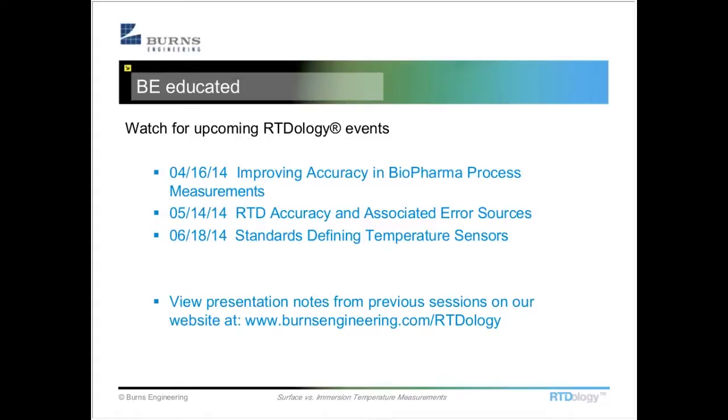We also see in a lot of cases where they used to have one temperature measurement on a system or on a pipe, now they've got 2, 3, 4, 5, trying to characterize exactly what's going on in the process, as far as whether there are any thermals going on. Because at the beginning of the pipe, it's this temperature. What's the temperature at the end of the pipe? Really trying to get tighter and tighter control of that temperature.